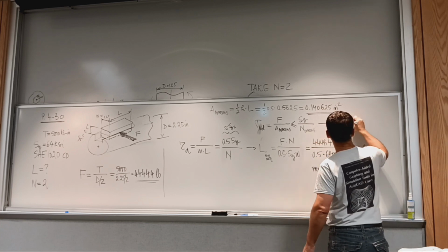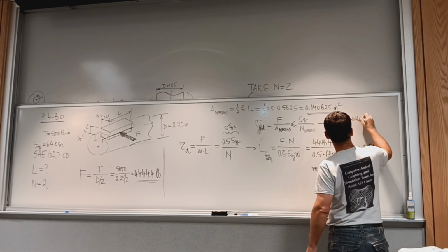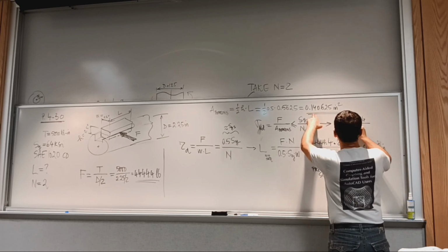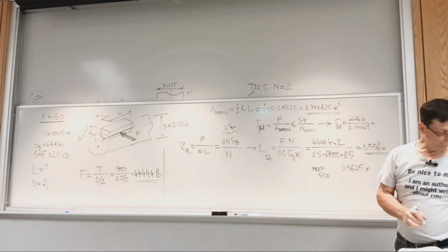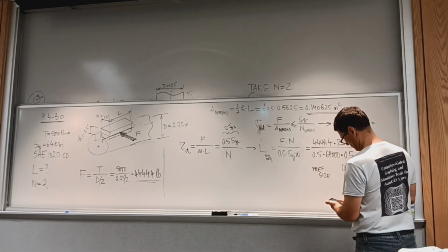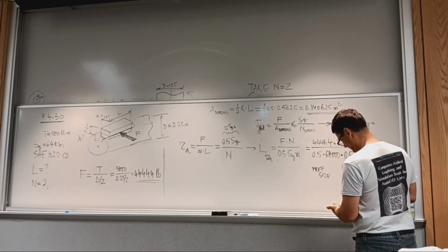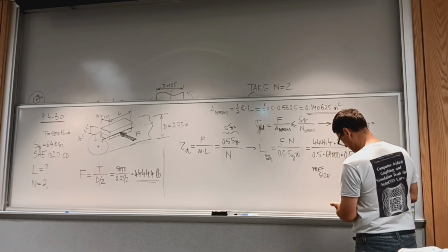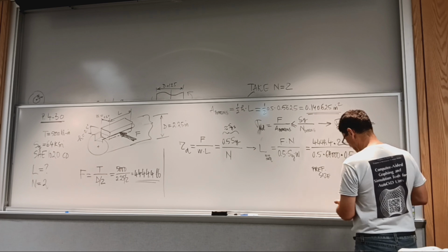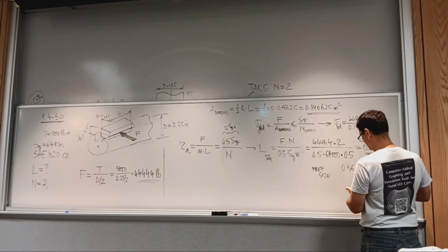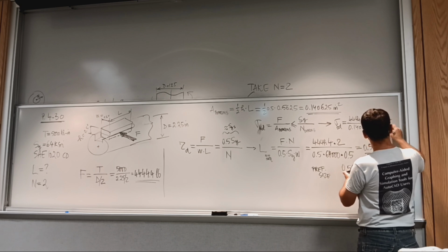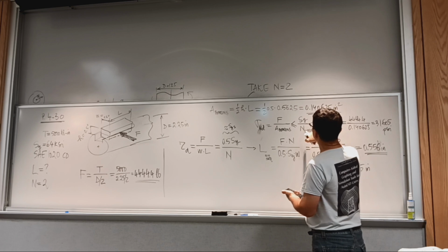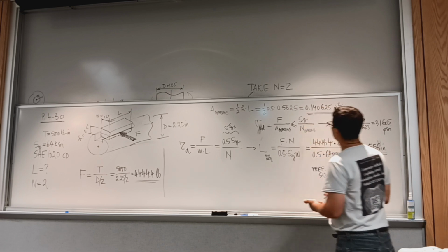Force, we have it, 1,234.4 over the area that I put in the memory, 0.625, so take the inverse times 1,234.4 equals, okay, so I have 31,605 psi.